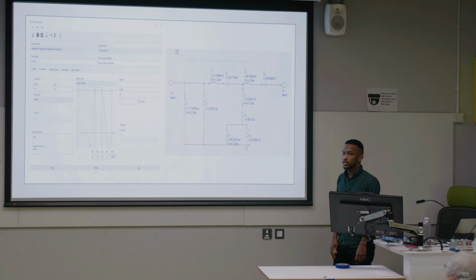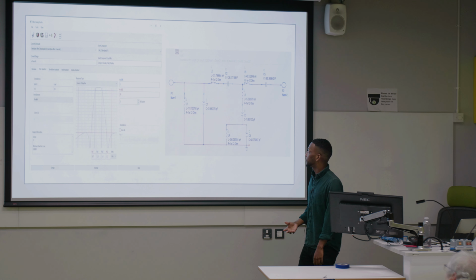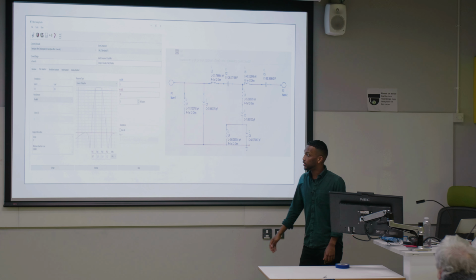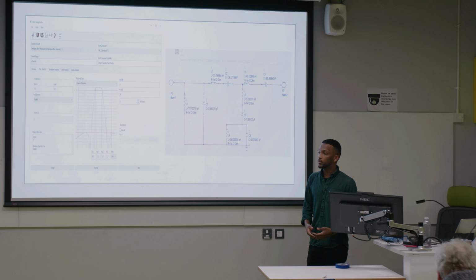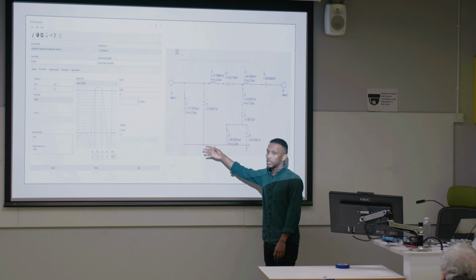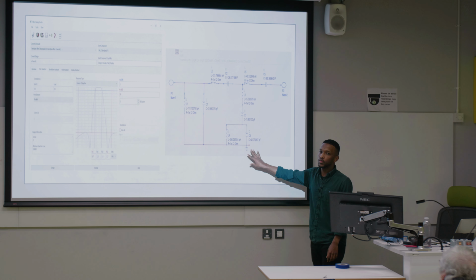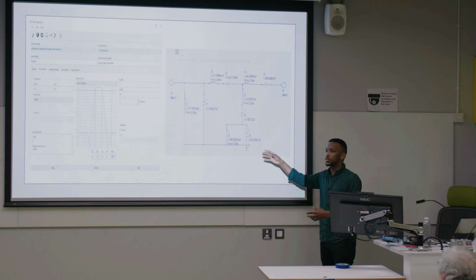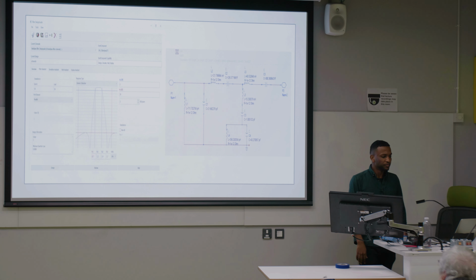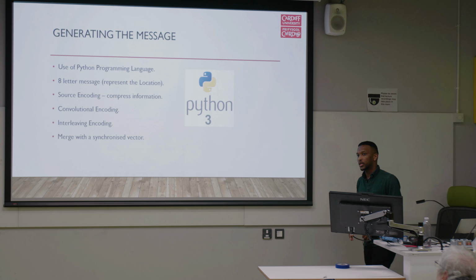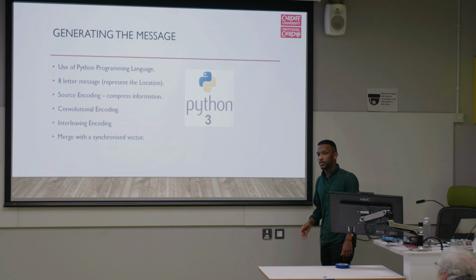One problem with this is it gives us theoretical numbers. It doesn't actually give us practical values of the lumped elements on this circuit. So the next challenge for me is to look at the practical components, compare them to our theoretical ones, simulate the theory, simulate the practical, and try to get the response as close to the theory as possible. That's with the bandpass filter.